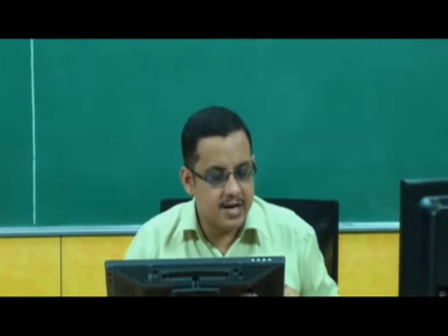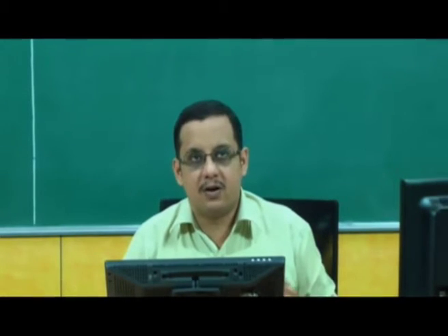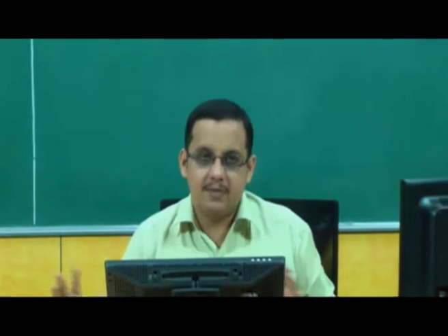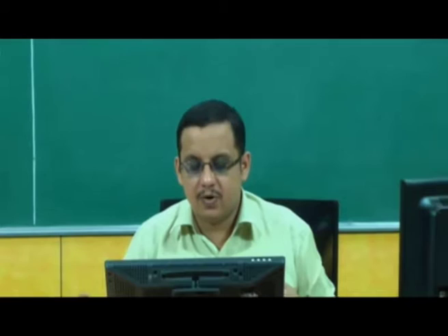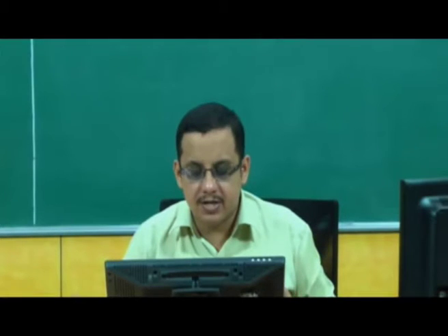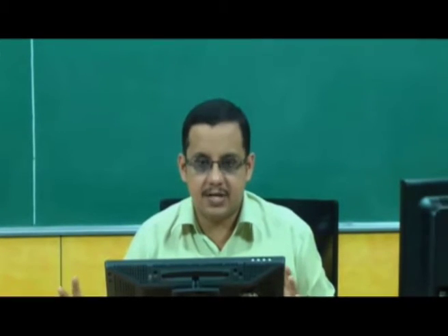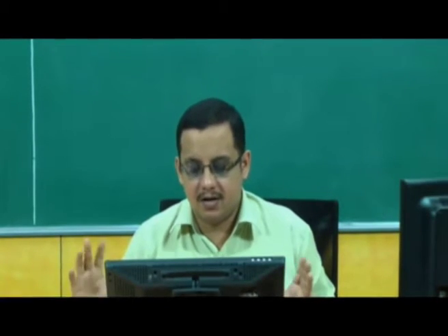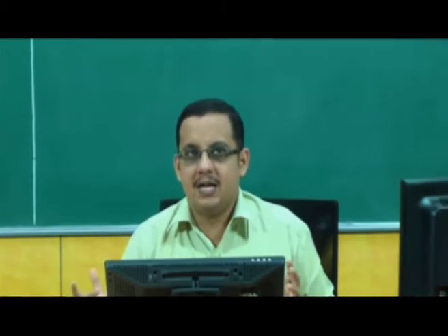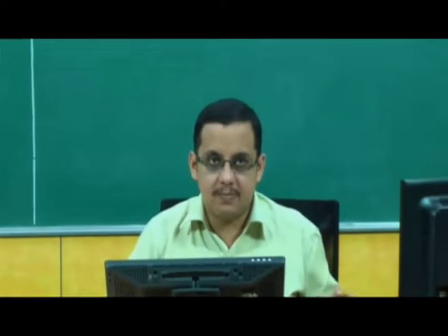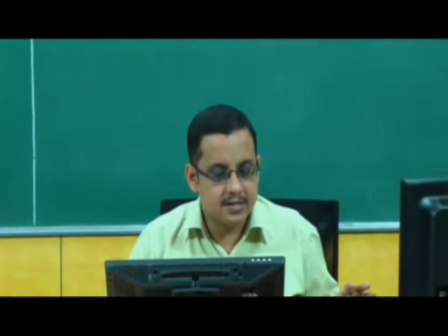KECP is asking why the driver and driven diameters are not the same in the cross-belt pulley analogy. Obviously, if the driver and the driven diameters are the same, then the velocity ratio is unity. But you want the cross-belt pulley drive to work for different velocity ratios. So to get a velocity ratio other than unity, you need the driver and the driven to have different diameters, which is what I showed in my drawing. The cross-belt pulley analogy works for any velocity ratio between the input and the output, and that is what has been shown schematically in the diagram. So I take that as answered.